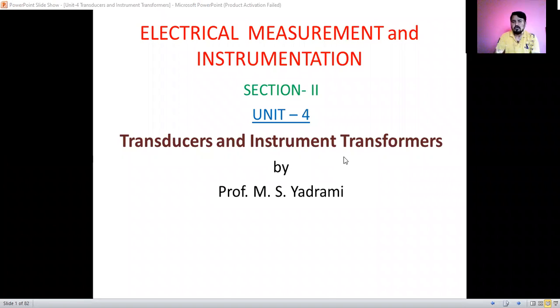No. So that voltage we have to reduce into measurable voltage and measure that. Then according to the ratio we have to calculate the voltage. So we can measure the high voltage in the form of low voltage. For this conversion purpose, we use instrument transformers. Those instrument transformers are the potential transformer and the current transformer. These two transformers we are going to use in this chapter.